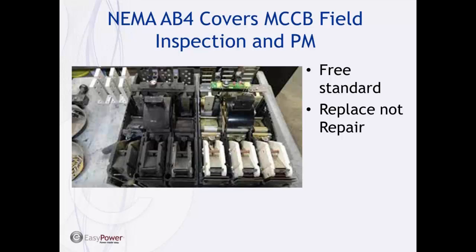So that's the basis for what's covered in the NEMA standard. I'm not going to get into detail on that. That's probably another webinar in itself. But keep in mind that there are some criteria for judging when your breaker needs to be replaced. Obviously, if you see burn marks around the breaker on the outside, around the arc chutes or the terminals, that's a pretty good indication. Or if you try to open the breaker and it stays closed, then that's another problem, right? So anyway, you might want to refer to this standard and the IEEE standard I mentioned for more information about how to deal with your actual breakers in the field as they get older and older and older.